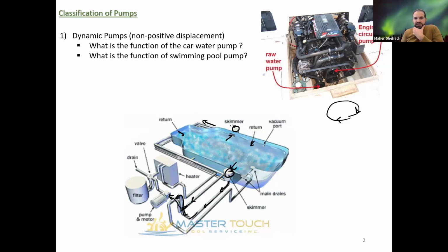So the water gets pulled back by the pump. It comes to the pump, and then the pump needs to push that water through the filter, the heater, whatever other system, and then overcome the friction in the supply lines. These are called return lines now because it's going to go back into the pool. We also have drain lines in addition to skimmer boxes.